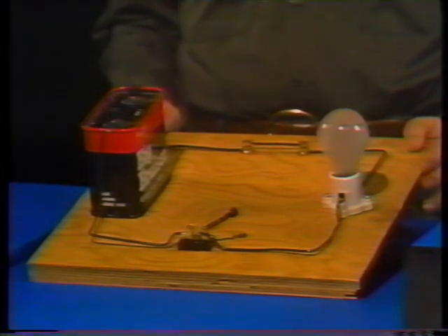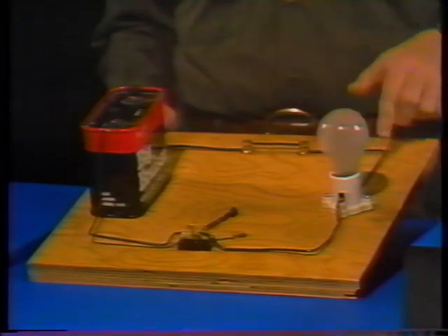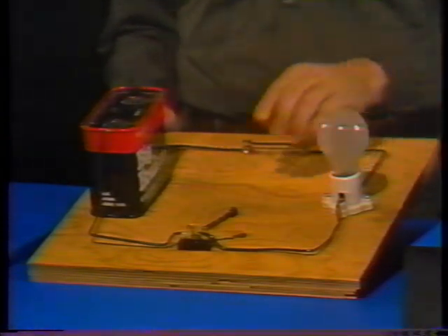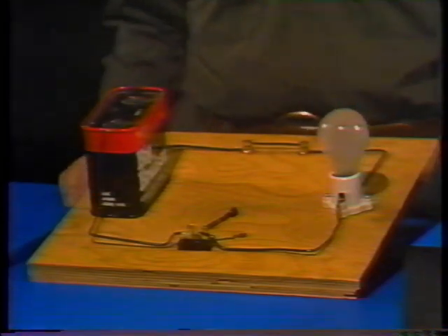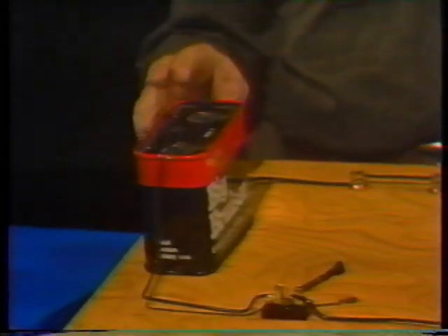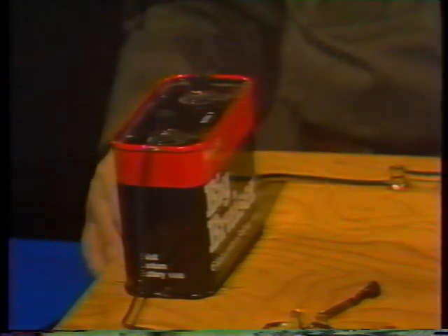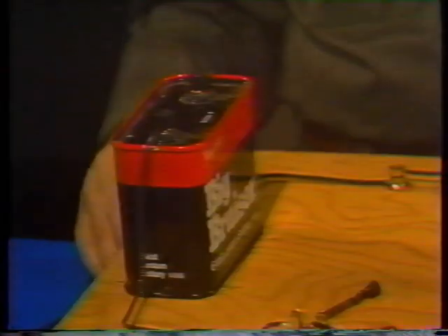When we use the term circuit, we really mean the path that the current follows. As you know, this circuit is made up of a battery, a light bulb, a switch, and a length of wire to connect them together. A good way to think about the battery in this circuit is to consider it a source, because it's the source of the electricity in the circuit. The battery supplies the voltage or force that causes the electrons to flow. The flow of electrons, as you know, is called current. The symbol for a battery in a schematic looks like this.